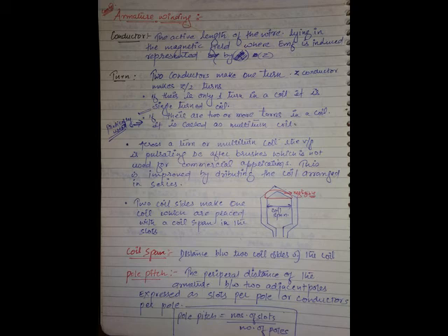Only 15, right? So like that, what you are reducing is the armature periphery. If you have a large number of slots, 60 slot armature, it has a large diameter; 30 slot armature, small diameter. So finally, you are utilizing the slot area effectively and making the machine compact. So generally, double layer windings are preferred over single layer windings. Single layer windings are only for small machines, but generally double layer is preferred.